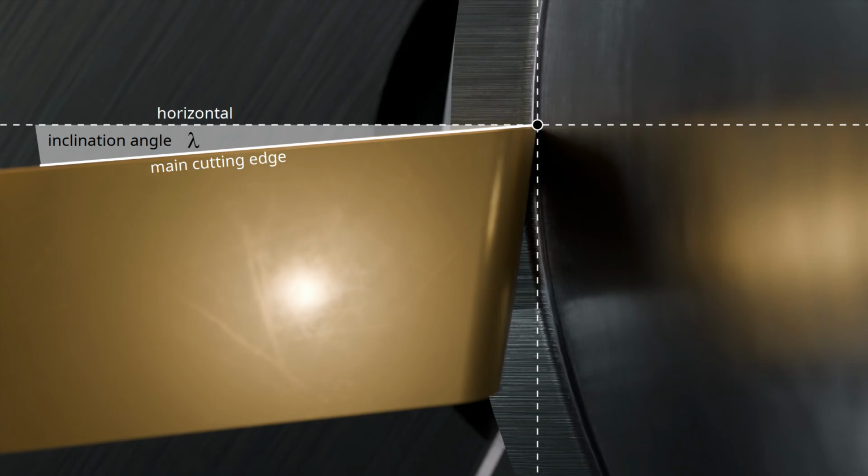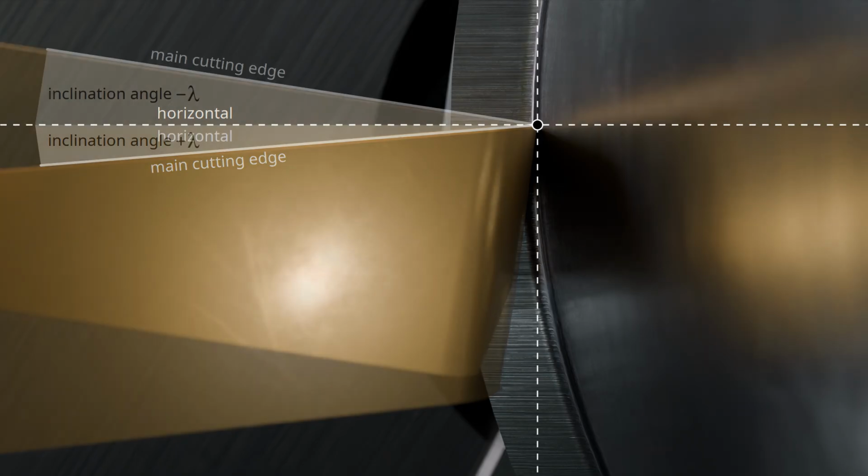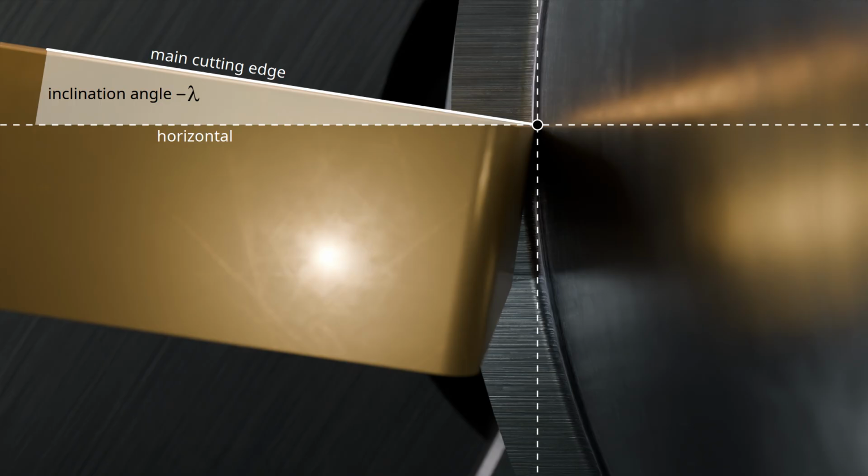Like the rake angle, the inclination angle can be either positive or negative. With a positive inclination angle, the main cutting edge, as shown, slopes downward in the radial direction. In contrast, with a negative inclination angle, the main cutting edge rises outward in the radial direction. A negative inclination angle causes the material to be cut not at the tip of the cutting edges, but further outward. This reduces the load on the cutting edge corner and decreases the risk of cutting edge breakage.